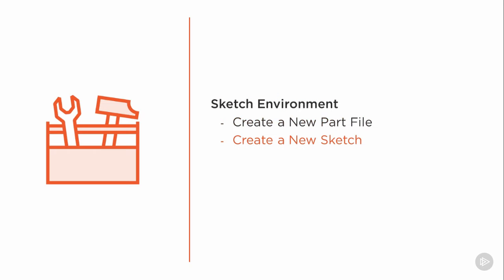The next thing we'll want to do is get familiar with the sketch environment in Inventor. In order to do this, we'll need to create a new part file. We will then create a new sketch on one of the origin planes, and once we're in the sketch environment, we can examine some of the sketch tools available in the Sketch tab. We'll also identify where to find sketch-related settings that you want to be aware of.